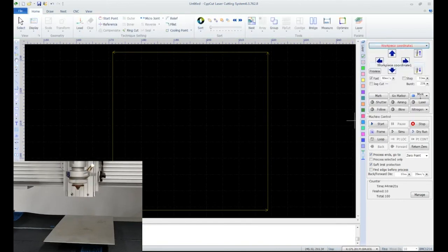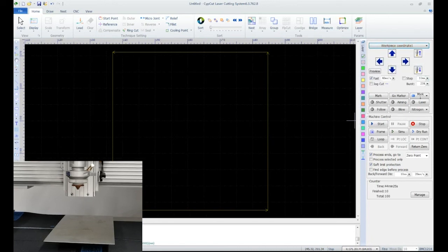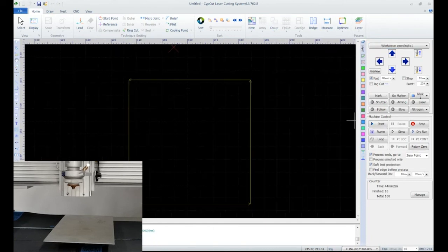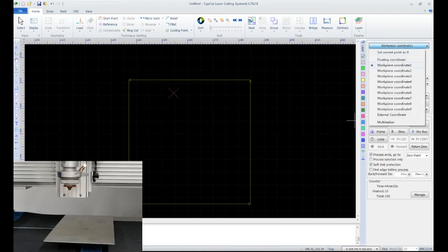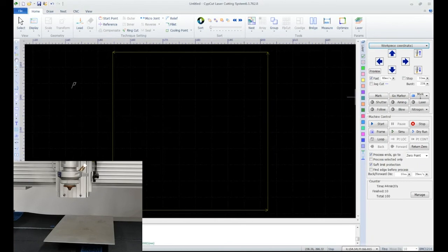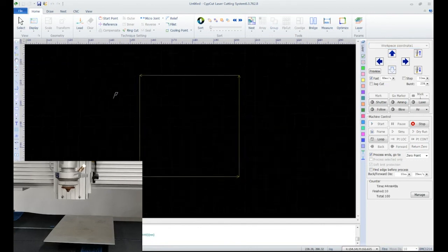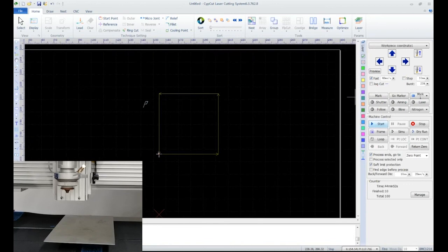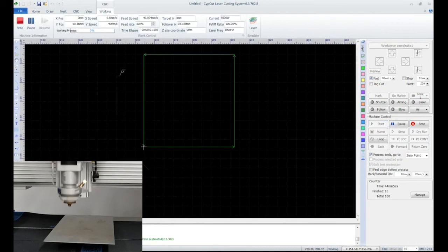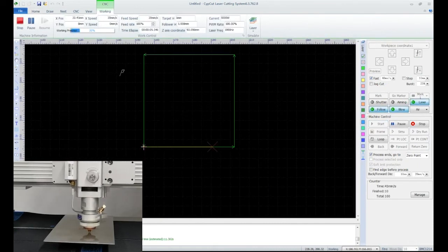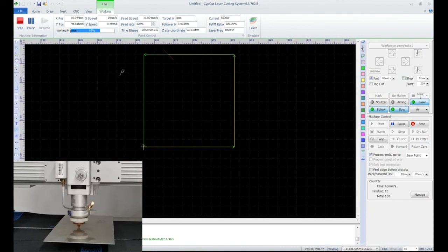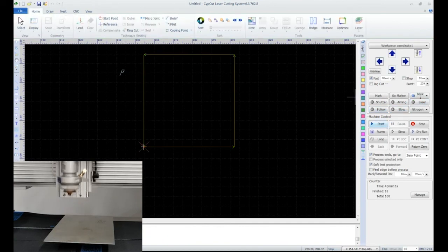Under workpiece coordinate, we've got a default 0-point with its position 0, 0. But 0-point is a user-defined position under workpiece coordinate. CypCut allows users to set 9 workpiece coordinates of different 0-point. During the process, if the cutting head was moved to another position, so long as it gets an instruction to start, it will return to the graphic next to the defined 0-point, and then start cutting. This coordinate is used in mass production scenarios where a large quantity of plates of the same size are placed in the same position on the machine bed, which also requires a 0 point of fixed position.